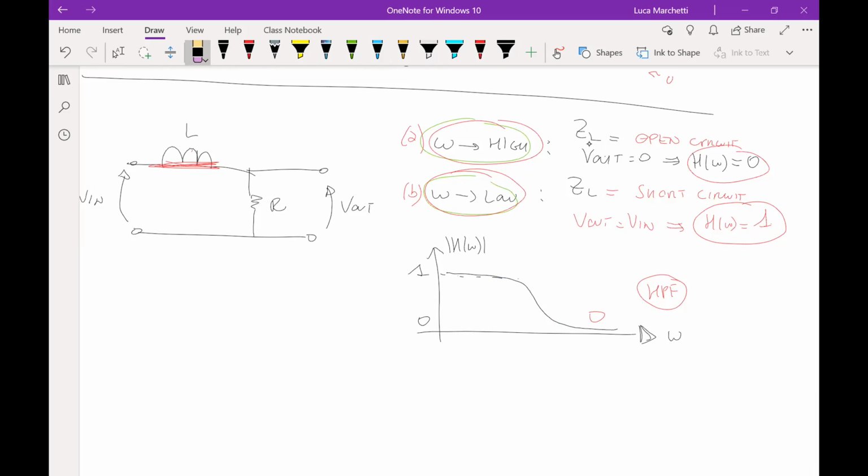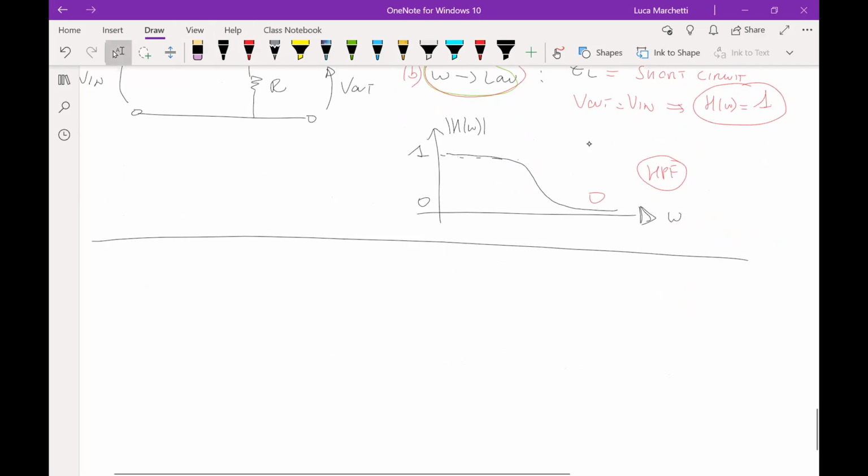And that will come out with the Laplace transform. If you know the Laplace transform, then you can draw any frequency response that you want of any filter, whatever it is, and you can draw it quite precisely, relatively speaking. So that's why the Laplace transform is very important in our case, and I think it's very important you understand the mathematics behind it.